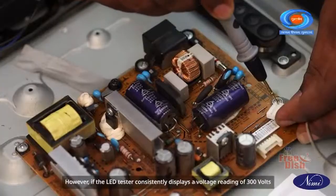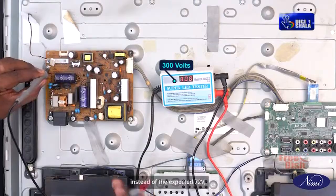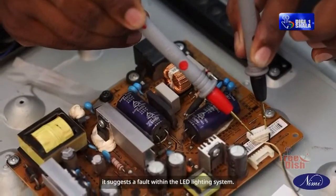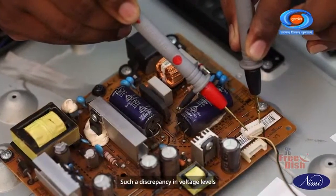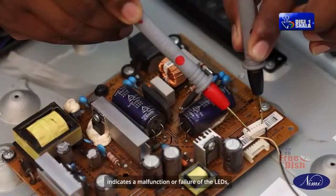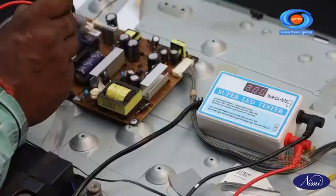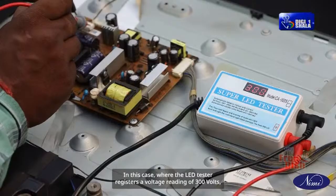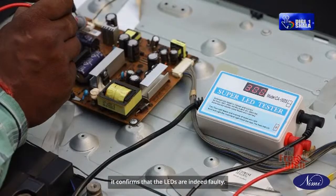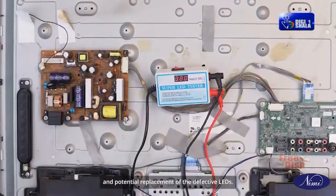However, if the LED tester consistently displays a voltage reading of 300 volts instead of the expected 72 volts, it suggests a fault within the LED lighting system. Such a discrepancy in voltage levels indicates a malfunction or failure of the LEDs, resulting in improper backlighting. In this case, where the LED tester registers a voltage reading of 300 volts, it confirms that the LEDs are indeed faulty. This diagnosis highlights the need for further inspection and potential replacement of the defective LEDs.